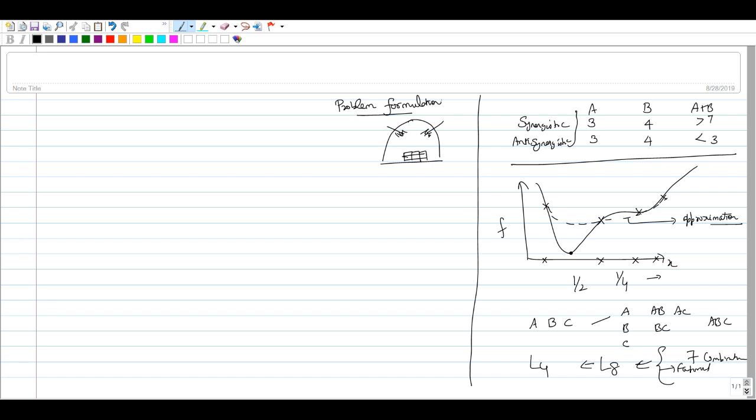But the way in which we dealt with that issue from a robust design perspective was we never worried about the furnace or the source of heat. We said that the respective things will be the same, and you just have to make sure that you are getting the dimensions. So that is essentially the idea behind robust design. You are not eliminating the cause of the variation, but you are still going to reduce your variation. So irrespective of your input, your output variation is minimized.